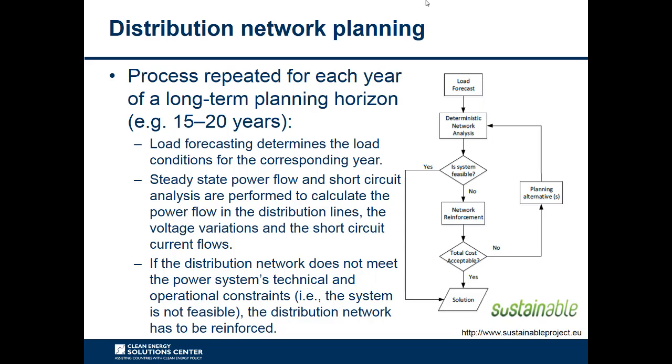This is a detailed technical study which allows the distribution system operator to understand the state of the system with the existing power demand and also with future power demands which are being considered. This can be repeated for the future scenarios they are taking into account with the load forecast for each different year, and also looking at different specific seasons of the year where the load can be increased or reduced.